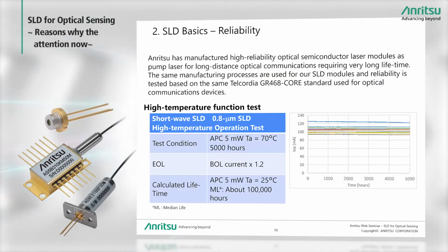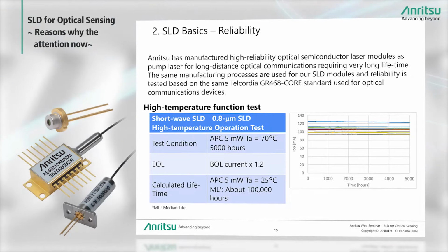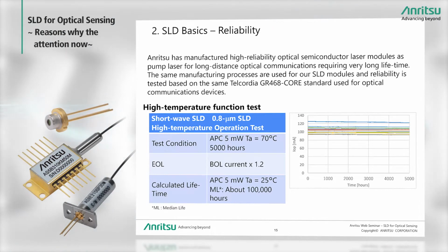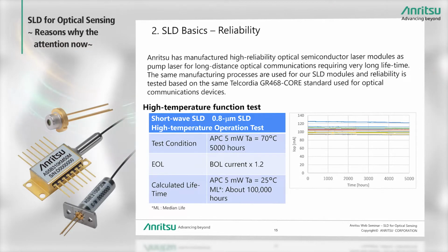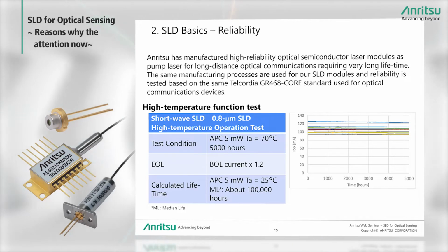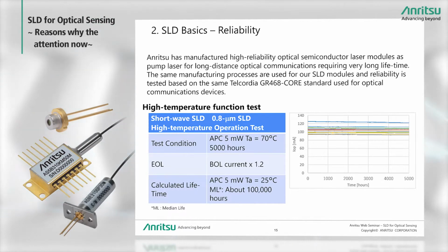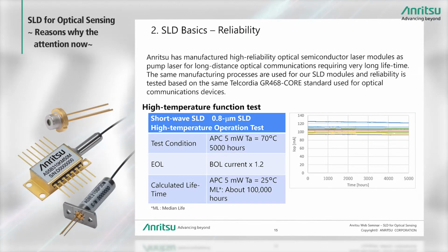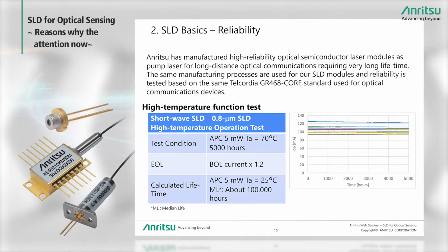This slide explains the reliability testing. Anritsu has long experience in manufacturing high-reliability modules for pump laser for long-distance telecommunications. The SLD manufacturing process is the same, and we test reliability based on the Telcordia GR468 standards for telecommunications devices.